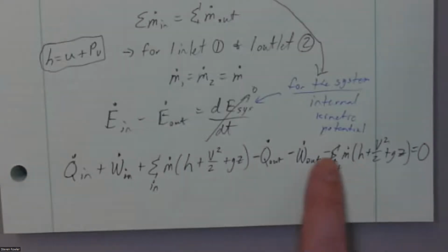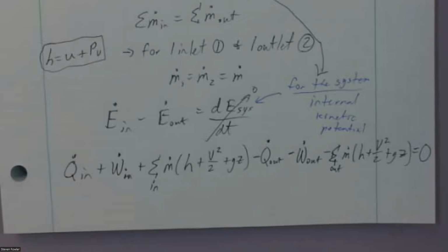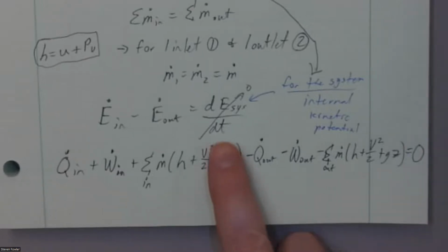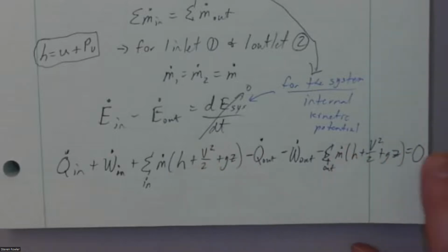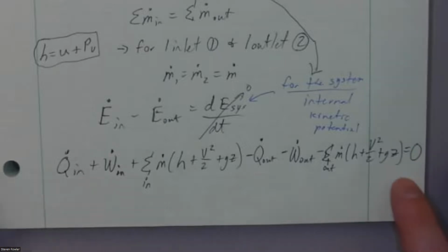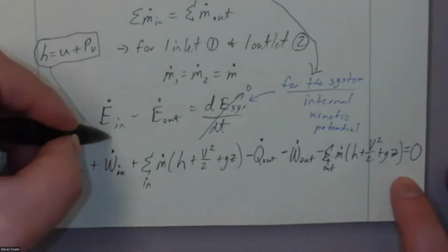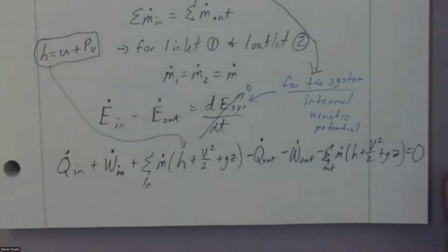That doesn't mean it's not changing from the inlet to the outlet. Those will change. So I've got water coming in, it gets heated up, and I've got hot water going out. The energy here will be different from the energy there for the water, but not necessarily the system. The system's flowing steadily. Okay, this is why it's not just a u value, because it's flowing.